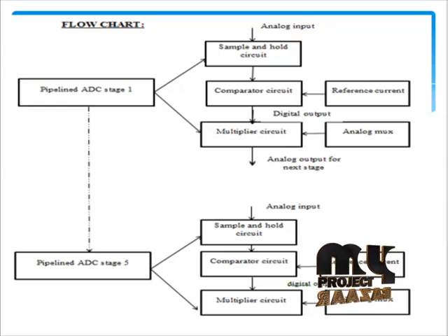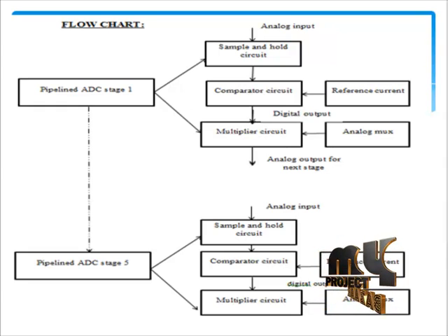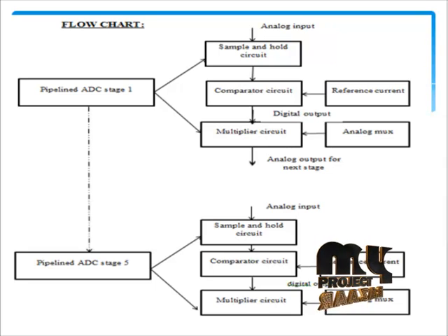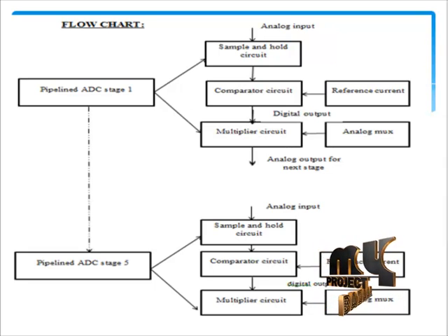A multi-bit stage can be used, however a high bit number is limited by offset in the comparators, so we are using flash ADC comparators. In this design we use a 4-bit flash stage, a 3-bit stage and a 2.5-bit stage. We have defined the stages step by step with a low-cost foreground calibration. The calibration is performed in the comparator sections, and we get the reference voltage from there.